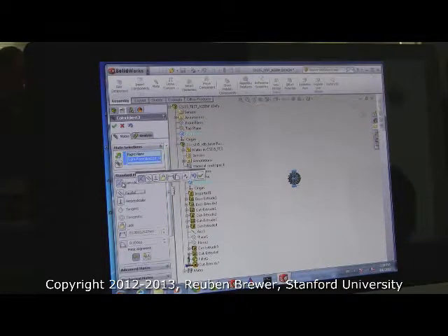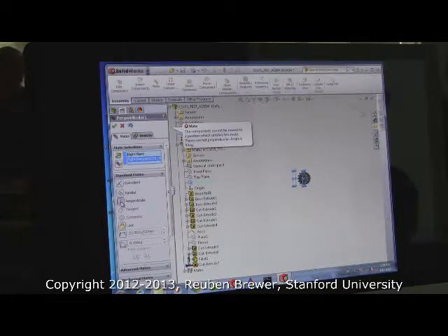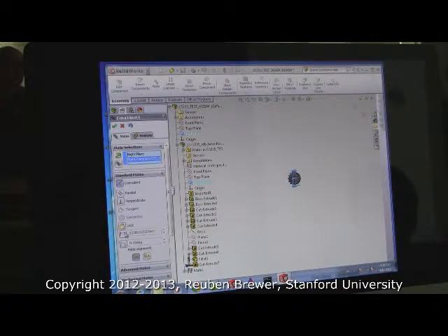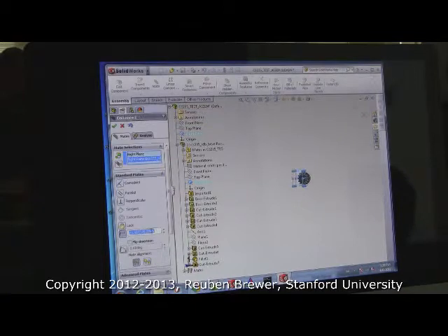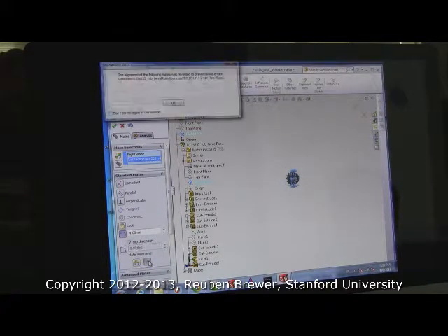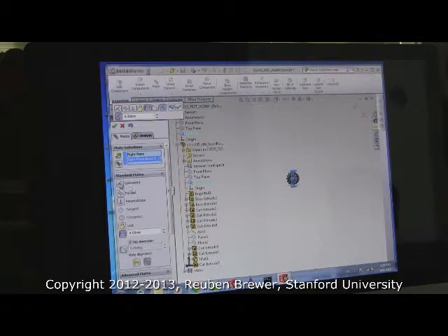This is coincident. I could do all types of things. I could do perpendicular. Actually, not for this. I could do parallel to make it parallel, but at whatever distance. I could do coincident. I can also see this button here, distance. I could specify I want it to be 50 millimeters away. If I want it to be on the opposite side, I can flip the dimension. I could make it 4 millimeters and flip the dimension. Instead, I just want coincident, okay?